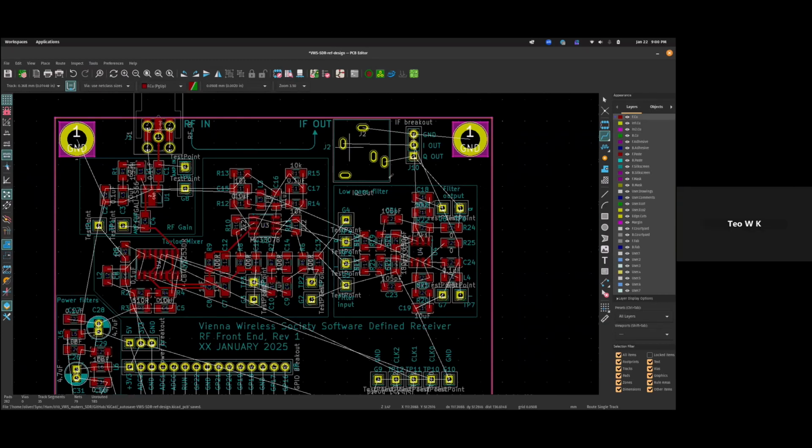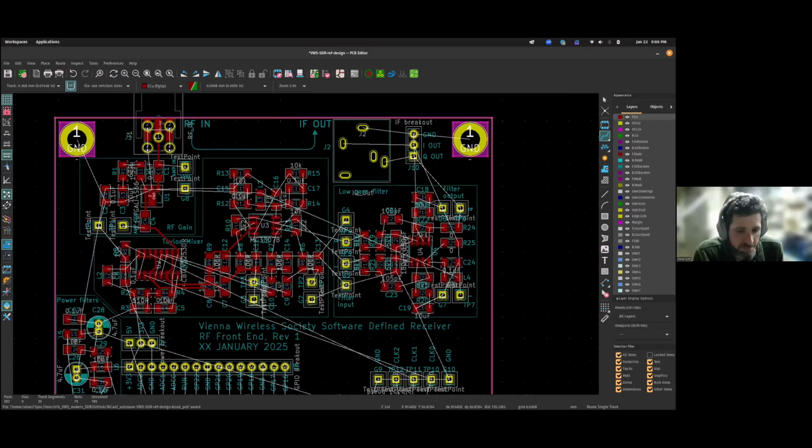So I saw how you would route the wire under the board in order to make stuff not cross over, but then you decided that that wasn't a good idea. Why isn't it a good idea to have stuff go under the board? It wasn't a good idea for that particular trace because it's an RF trace. It doesn't really matter at HF frequencies, but particularly as you get to higher and higher frequencies, just the physical act of transitioning from the top layer of a printed circuit board through the circuit board to the bottom can have insertion loss and discontinuities that are bad for RF signals.